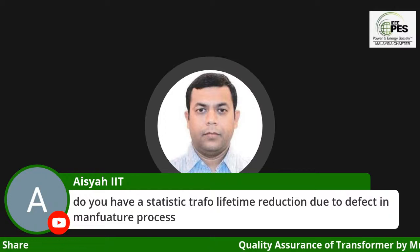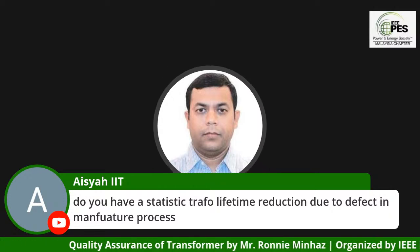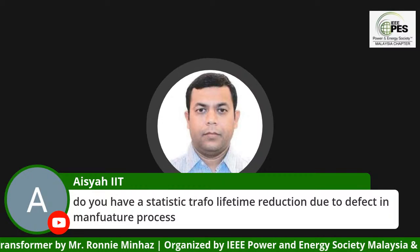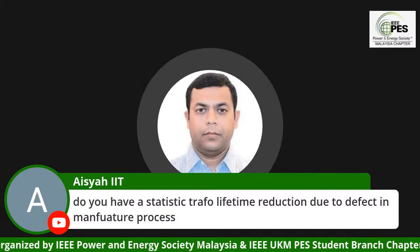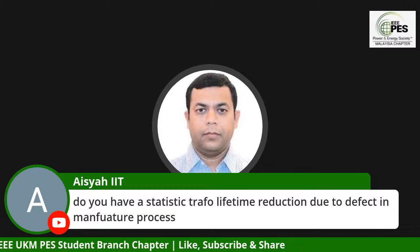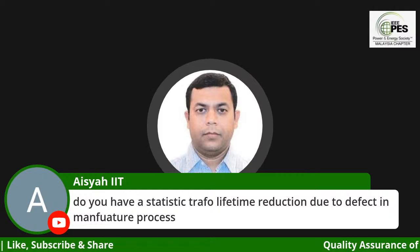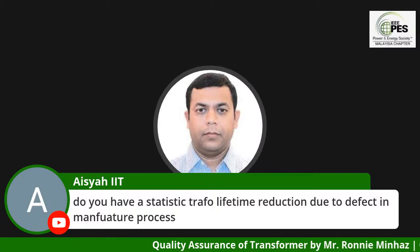as I'm being part of a transformer committee, as I mentioned to you, one of my colleagues who is a chemist has done research on that. What he showed in his research is that if you put the transformer into service, if you load it 100%, continuous loading, if the transformer average winding temperature rise is close to the 65-degree rise, and your ambient temperature is close to the max 40 degrees, in this case, the life of the transformer will be 7 years.